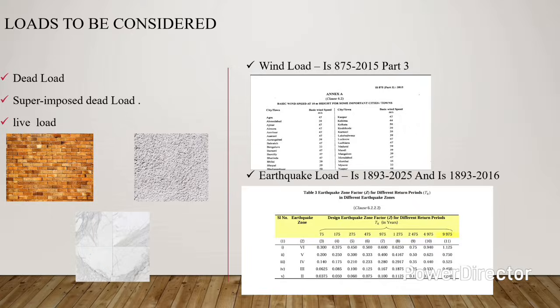Okay, so before starting the load calculations, first we have to see the loads to be considered in the analysis of the structure. So these are the important loads which I have mentioned in the slide, which we use in the analysis of the structure in any software or even manually. So dead load, first we see dead load. As we know, while analyzing or designing the structure, we calculate the self-weight of the structure, and self-weight is an important concept in structural analysis and structural design. So we will define the self-weight of the structure. Here dead load specifically means the self-weight of the structure. So in ETABS, self-weight will come under the type dead load while defining.